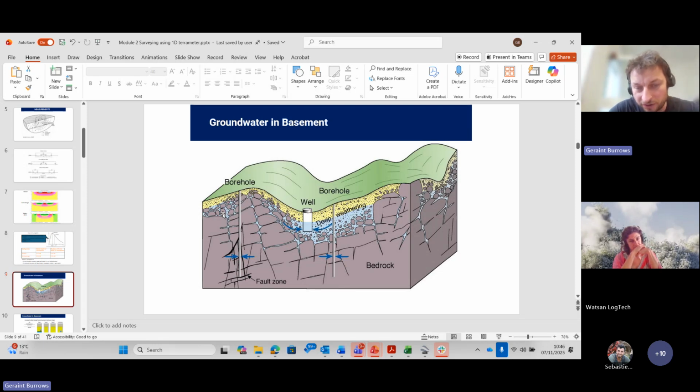The way that we would look at it, before going in to do a geophysical survey, I'd be keen to understand the structure, the geology itself, and then look at the different history of the structures. There might be some fractures that are more recent that are water bearing compared to older fractures that have been closed up, depending on their strike direction.